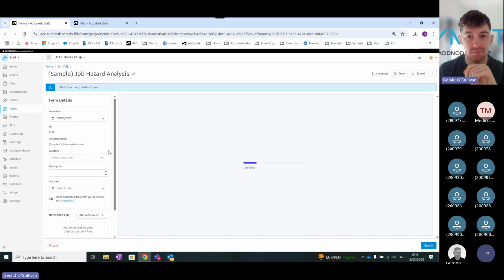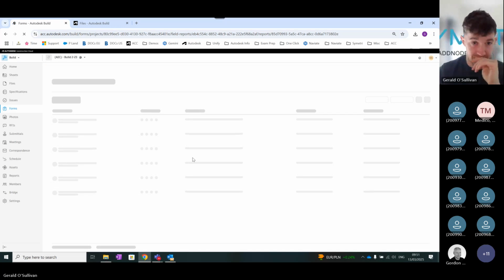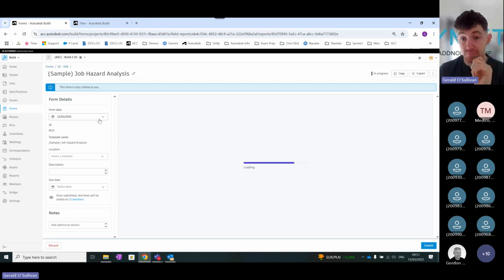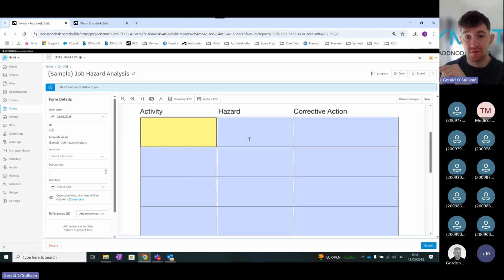You can convert the PDF that you would have created in your Word document to what's called a Smart PDF. How you convert it to a Smart PDF is you can use the likes of Bluebeam. So Bluebeam will allow you to basically convert the cells in the PDF into intelligent elements, where you can actually type in the information that you need inside here.